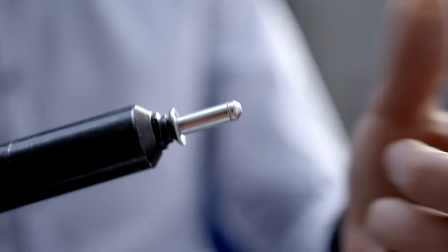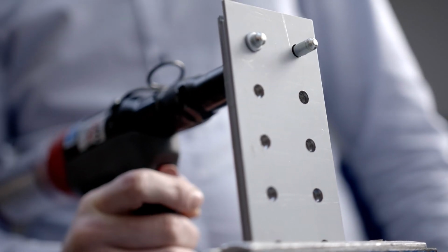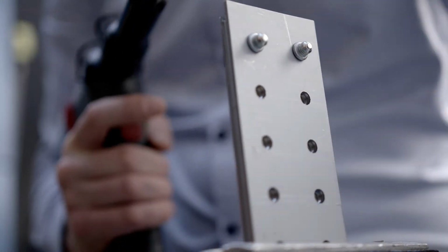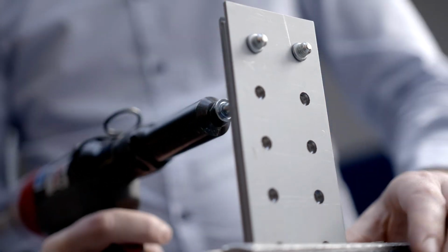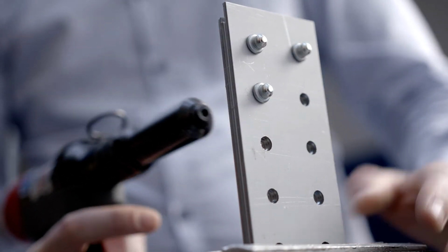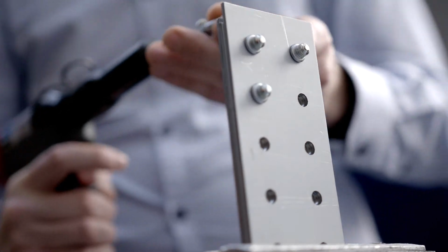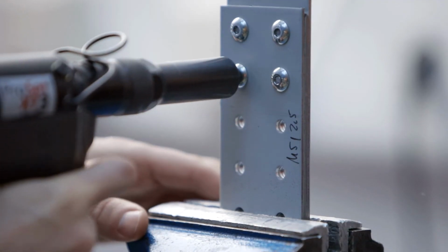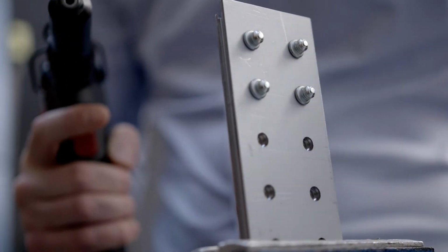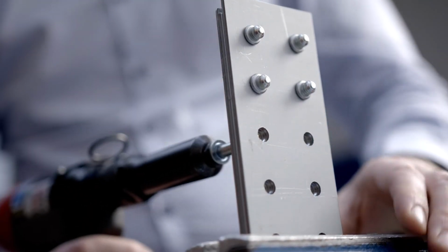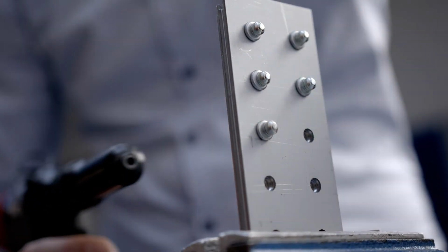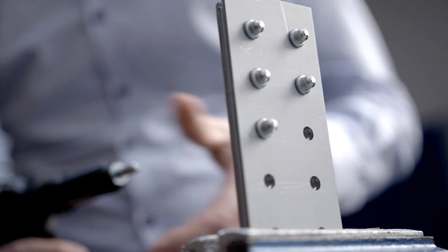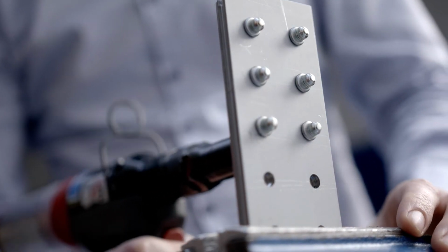With blind rivets, you are able to fasten 2 or more application materials permanently together. One of the main arguments in favor of blind rivets is that the process only requires one-sided access. This is a huge benefit because fastening solutions normally require 2-sided access. Their integration is reduced to work on individual parts or involves considerable setup costs. There are many different blind rivet types on the market, with different functions and different advantages.